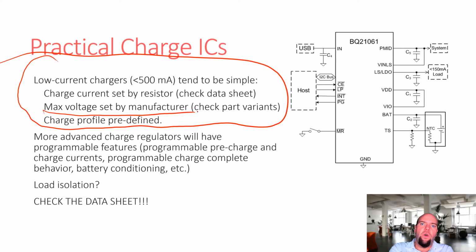And again, it's a matter of knowing your battery, knowing your particular battery chemistry, and knowing your design. Some designs, they say, this thing is never going to be recharged 1,000 times. We don't have to worry that much about the battery. But what we do want is to get as much energy out of the batteries as we can. Let's bump it up to 4.3 volts. Some of them say, nah, we want to be careful with this battery. We want to get as much lifespan as we can. Let's only charge it to 4.15 volts or something like that.